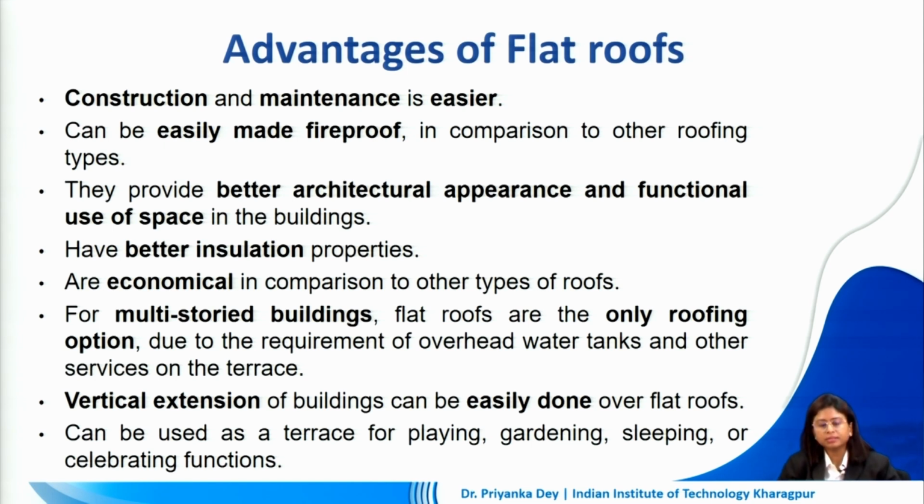Every few years we will have to treat the upper surface to ensure that the integrity of the roof is maintained. But though initial investment in a flat roof is higher, its durability and longevity is much more. It also doesn't require very regular maintenance. It can be easily made fireproof. That is one of the major problems with pitched roofs, especially the ones which are made with timber or thatch. They can catch fire very easily and can lead to devastating situations.